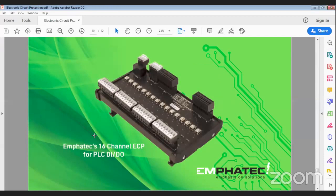We did a 16-channel unit. This was a prototype for a project where you can see there's a row of push buttons on there. And if any one of the 16 channels goes into overcurrent protection, shuts down, in other words, you would reset it by hitting that button. With an ECP product, you could design the circuit to latch off. You could have it reset as if it was a thermal supplemental protector. You could reset them by a remote signal.